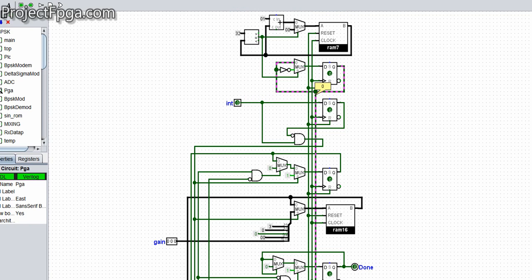Now, this int bit is our interrupt enable bit. It is used to send an interrupt signal. So whenever it comes on, it means that a transmit interrupt has been sent. That is more like a start button for the transmission to transmit this gain. So whenever you set the value of this gain, you set this interrupt enable bit here. Once the interrupt enable bit is sent, the transmission starts.